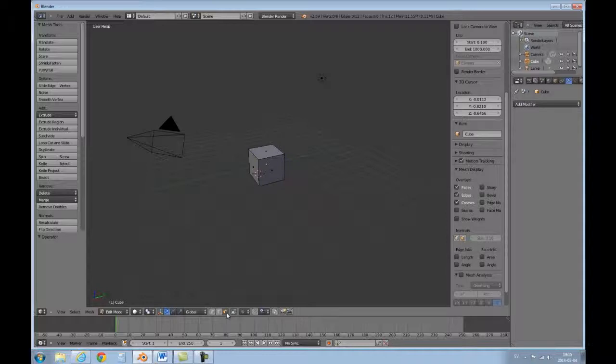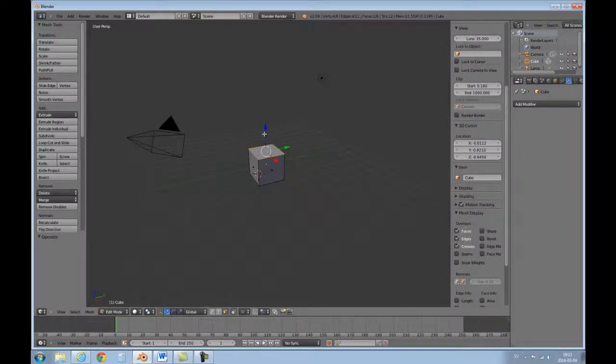Faces are flat, two-dimensional objects that can be moved, rotated and scaled, and there's a face, and I can move that, and it almost has the effect of scaling the object in the z-axis. I'm actually moving the face, and by so moving the face I'm stretching the rest of the object, because the face is attached to these other polygons here. If I rotate it, I can give this twisted effect.